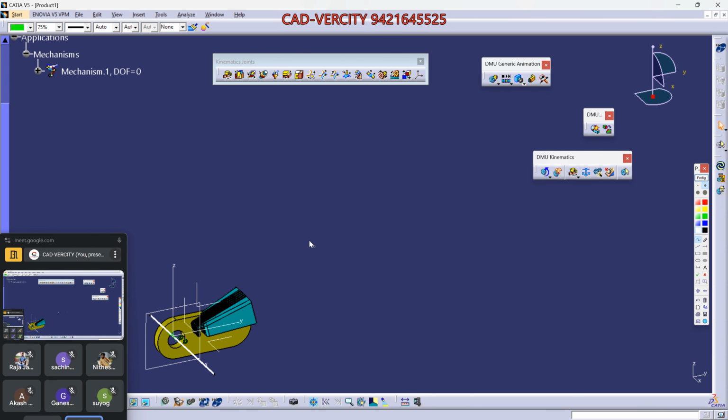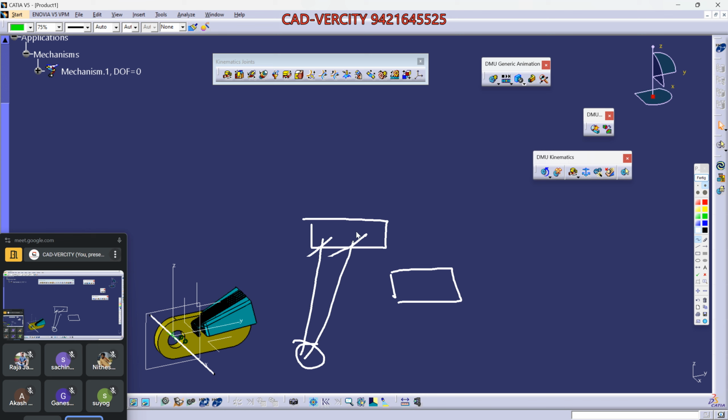In motions also you can give some limitations. Suppose this is a box and this is the axis of rotation like this. Let me erase this one. Your axis of rotation is something here like this, and if you want to rotate like this, it will be something like this. So you can limit this angle. You can put limitation. Let's say I want motion of only 25°. That's it. You can limit.